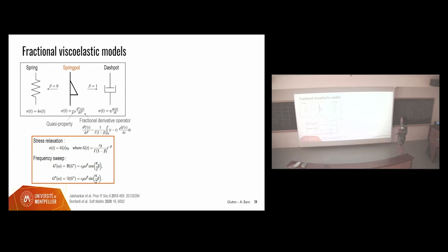And using the fractional derivative operator, you expect for a stress relaxation of a spring pot a power law decay of the relaxation modulus as a function of time, with the exponent here, which corresponds to the derivative order of the spring pot. Equivalently, for the frequency sweep, you expect power law dependence on the frequency.